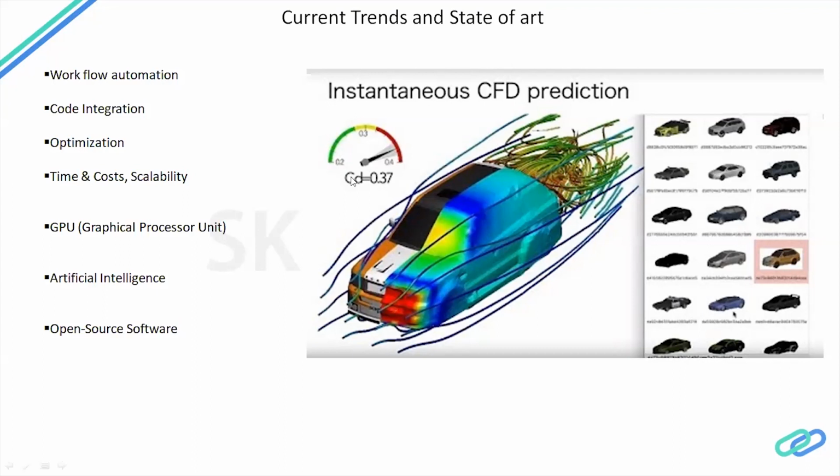If we reduce the air resistance, my fuel efficiency will improve as well. So we try to change the shapes, reduce the flow separations and change the styling of the vehicle, to reduce the CD value to 0.3. This type of activity is called optimization.